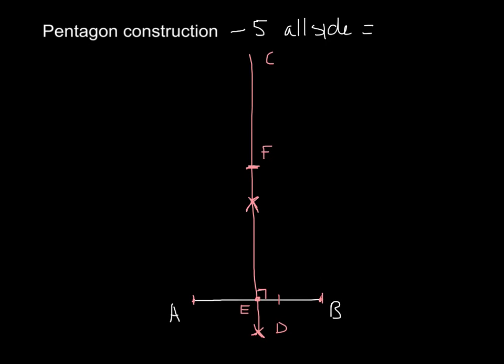Okay. Next step would be to take a brand new line from point A through point F, a light construction line, as long as we can take it. Right, now using line AF, we're going to mark off distance AE using our compass. So we're going to mark off the distance by putting our pin at A, moving to E. We're going to mark that distance off from point F to point G. Right, now GF will be the same distance as AE. We're just going to mark it off on there.